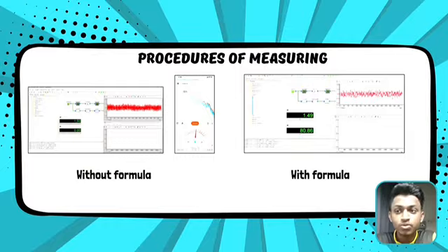Next, procedures of measuring with the formula. We have to get ready with the hairdryer and DASYLab software on laptop. For this, we won't be needing the Decibel X app on the smartphone. Next, we will be inserting the formula 20 log(in/0.001346) into the formula interpreter in the DASYLab. Make sure there is no noise interruption as well.